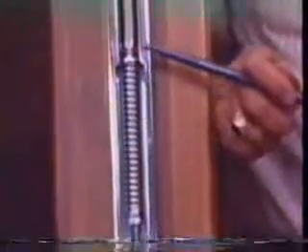The valve has the familiar upper packing and lower packing, and the casing pressure is always sent between these two packings. The casing pressure right in this area furnishes the large supply of gas which flows to the main inlet valve. Right here under the upper packing are the small ports that supply gas to the pilot. The casing pressure moves through these ports, upward, past the spring, and against the bellows.